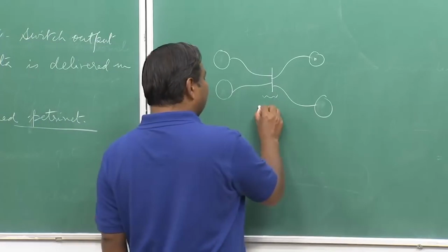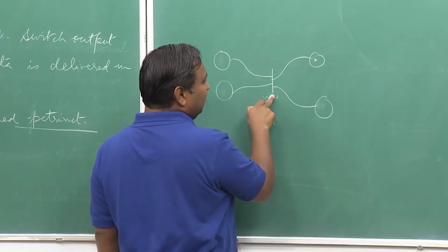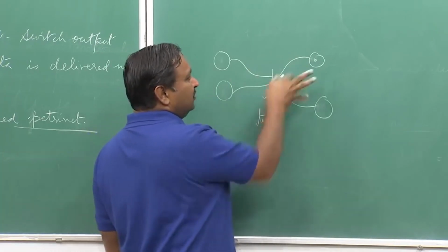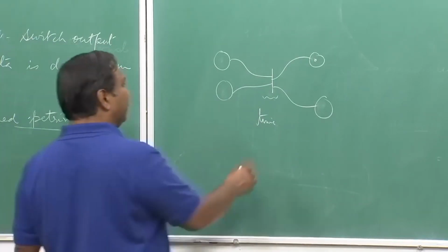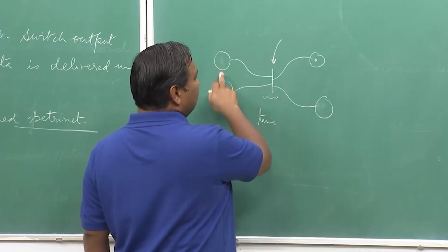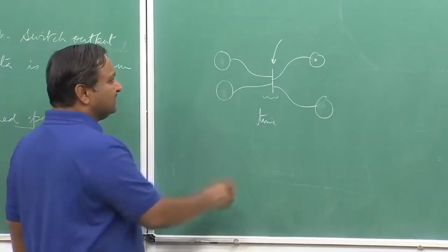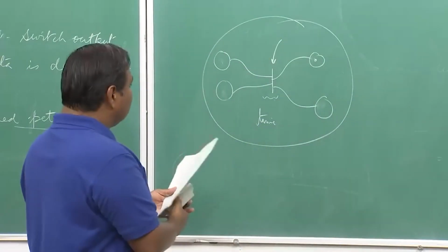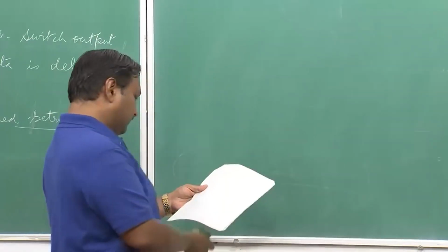I can also put a timer. If these two are available, after some time t the firing will happen, these tokens will be consumed and new tokens will get generated. So, essentially the idea is this decision thresholding mechanism, the token holding buffers, and token holding buffers on the outgoing side. Using this element we can create a model for a 2 by 2 crossbar. So, let us do it for a 2 by 2 crossbar which is a buffered system.